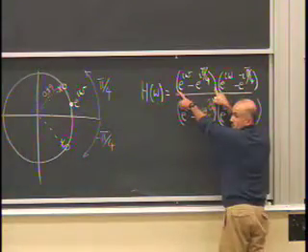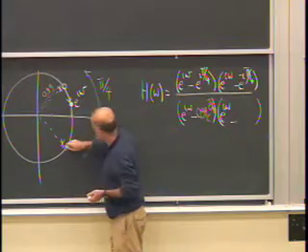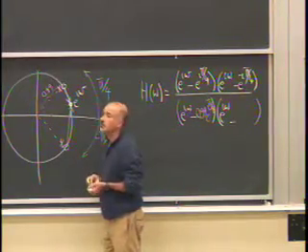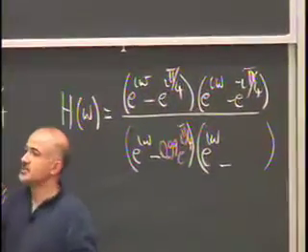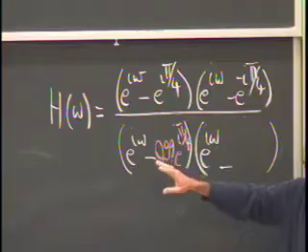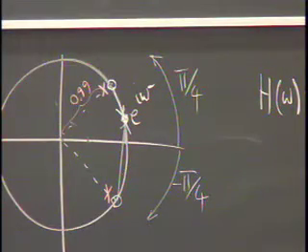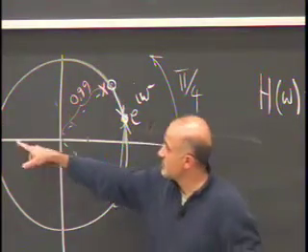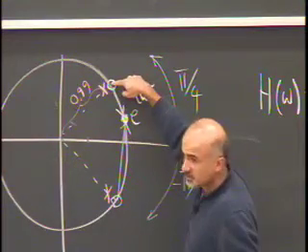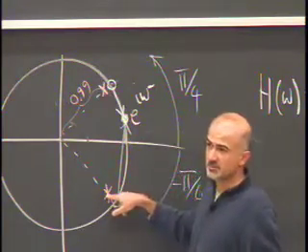notice what I have in the numerator. I have this vector, which is, sorry, the blue one. Your boss says, design me a notch filter such that when you want to implement it on the computer using the difference equation, whatever it ends up being, I don't want any storage, anything more than 2 storage units. That means my difference equation has to have at most 2. Or he tells you, give me the minimum storage. The moment you go off the omega equals 0, omega equals pi angle, you know that to keep the filter real, whatever 0 you put here, you've got to put the complex conjugate. Whatever x you put here, you've got to put the complex conjugate to keep it real.